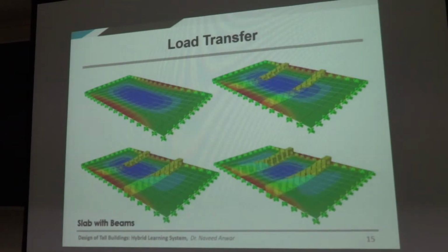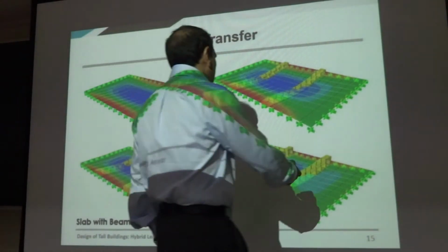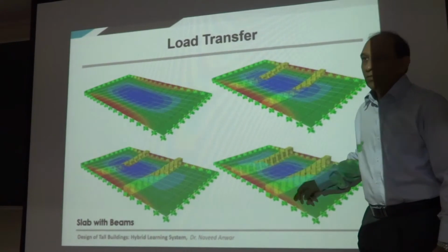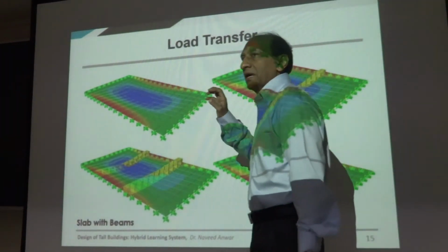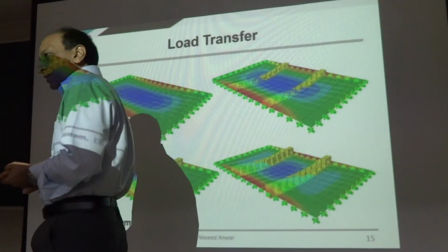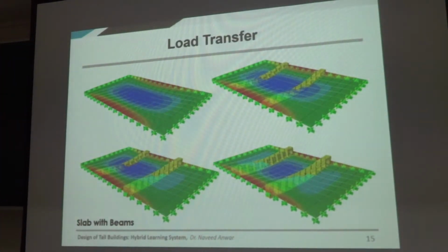And if the two beams are big, then you can see that it divides into 3 panels, almost, right? So that means big beams, small beams, and the relative stiffness is very important. But the question is, how big will the beam be before this happens? Wait for it.